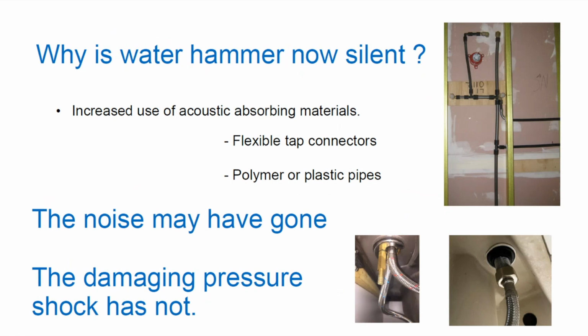And his takeaway message is, why is water hammer now silent? Increased use of acoustic absorbing materials, flexible tap connectors, polymer or plastic pipes. So the noise may have gone, but the damaging pressure shock has not. And so it is an important concept that must be viewed both in design and in analyzing water systems. Next.